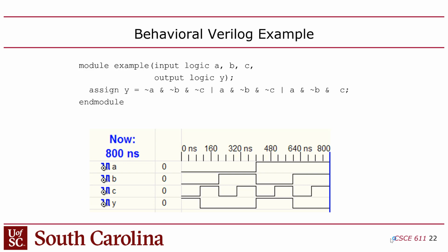analyzer. You're looking at a graph where the horizontal axis is time, and the vertical axis is meant to represent voltage, but it's binary. It's not analog, you just have two voltages. And so it's not labeled 0 and 5 volts, it's just high and low, because we could use any voltage to represent a 1. Could be 1 volt, could be 3 volts. Doesn't matter. I just have low and high, right?